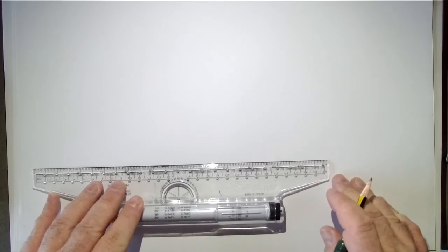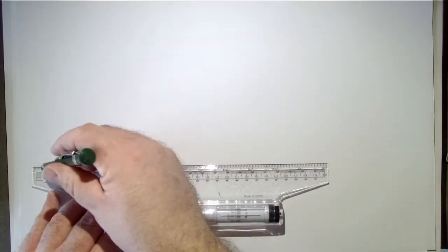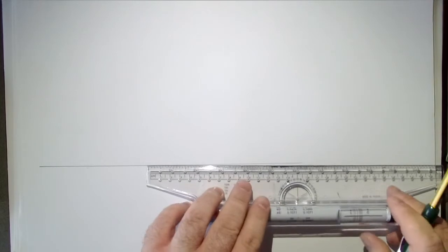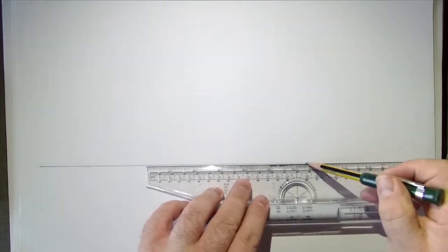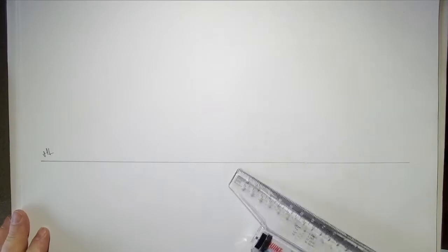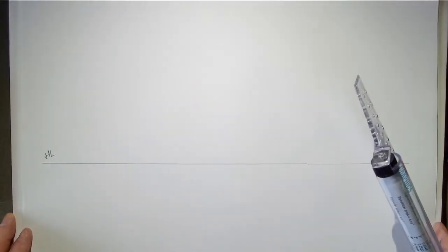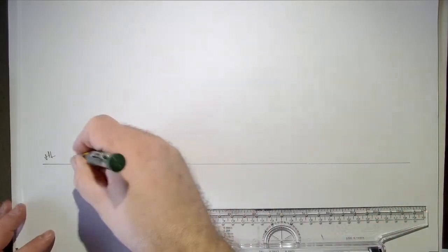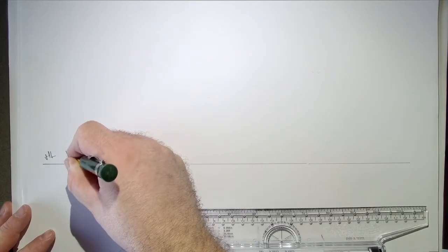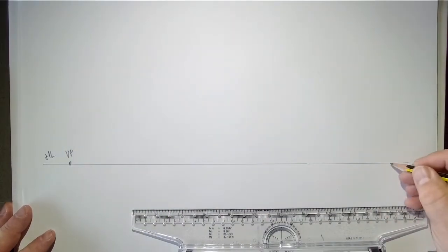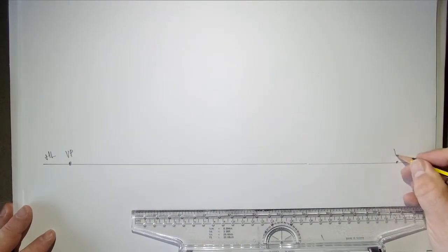With the 2 point perspective method, we begin as we would with the 1 point perspective method, by determining the horizon line. Everything originates from the horizon line. Where we place the horizon line on the paper will start to determine the character of the drawing. It's one of several variables that will determine the character of this drawing. I will now place 2 vanishing points as opposed to 1, on opposite ends of the paper.